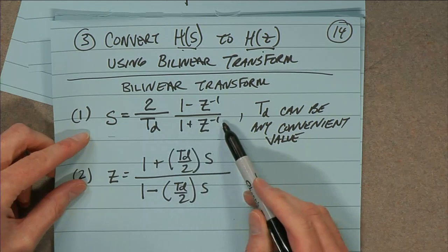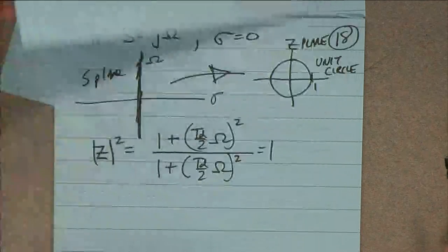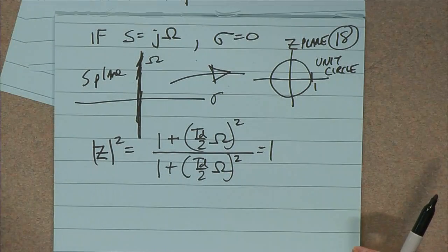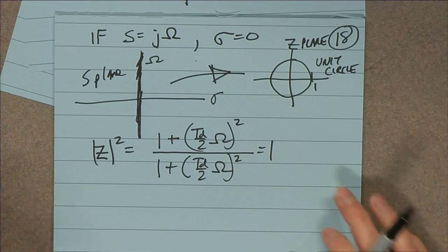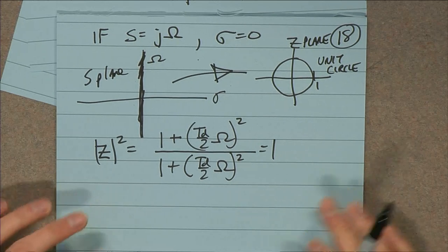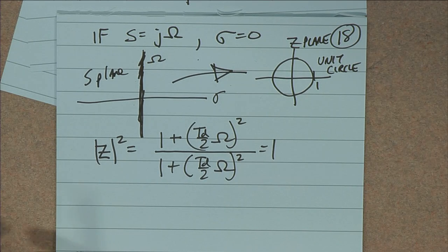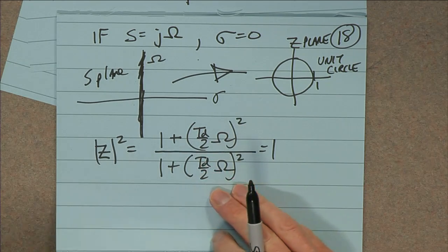This could get kind of ugly when you substitute it in. But really, it's doing all this warping and changing. But at the very beginning, I said it's kind of a 3-step process. The first step is changing the frequencies in discrete time to what are the frequencies in continuous time, because you need those to then design the filter. And I haven't talked about that relationship yet. So that's the next order of business.